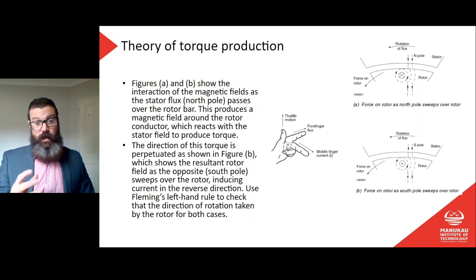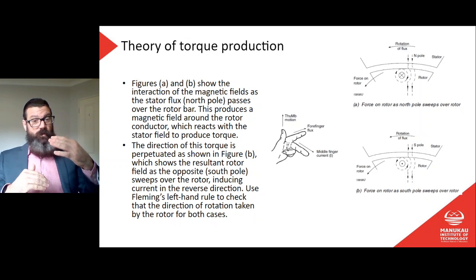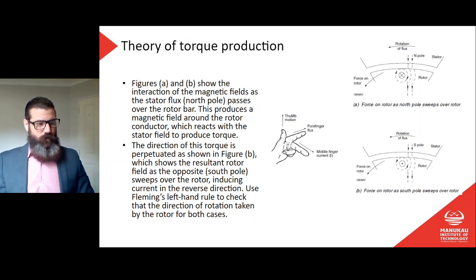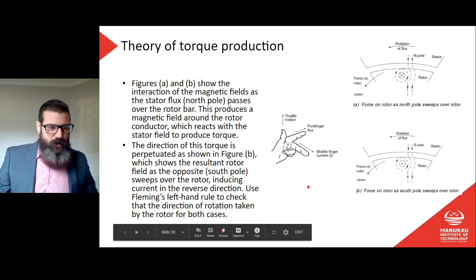And then it will stay there. If I take load off the rotor, then less torque is required, so the rotor will speed up. If I put load on the motor, it will slow down until it gets to the point where it's producing enough torque. Remember, more torque is produced at slower speeds until enough torque is produced that it will stick at that speed. And that's essentially what this is saying here.